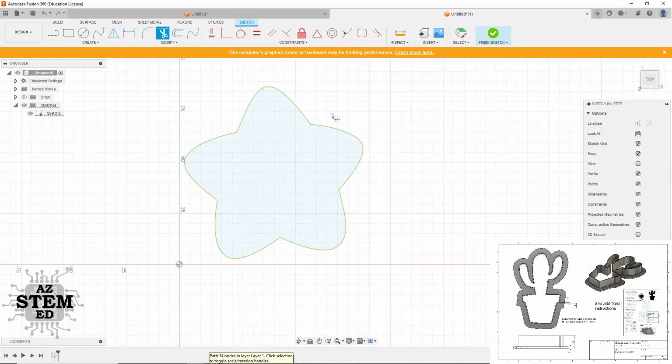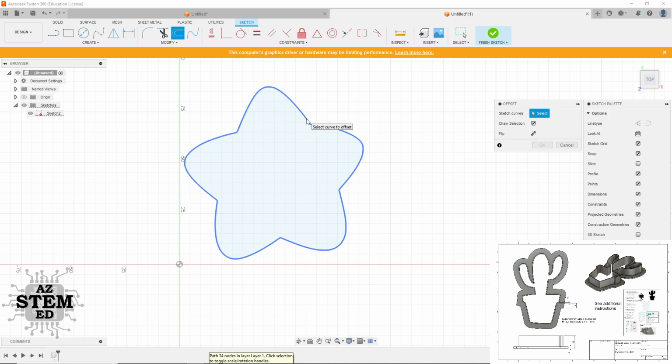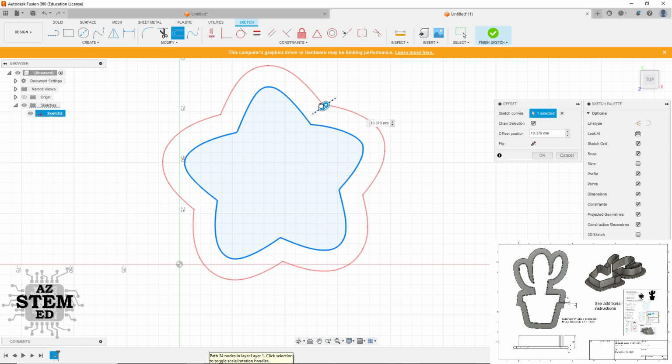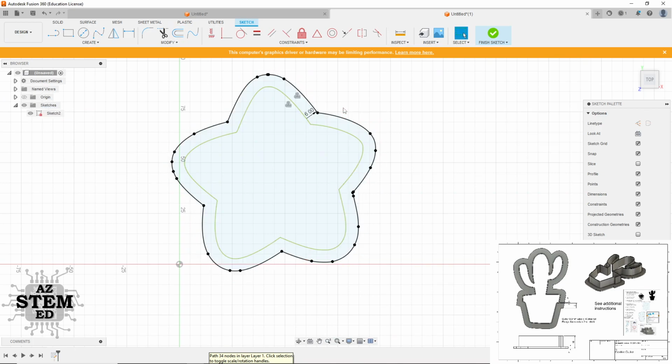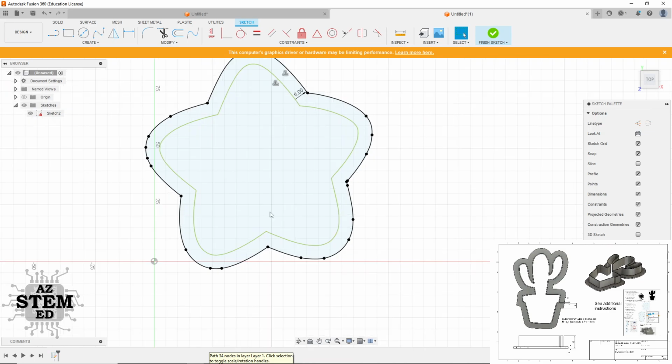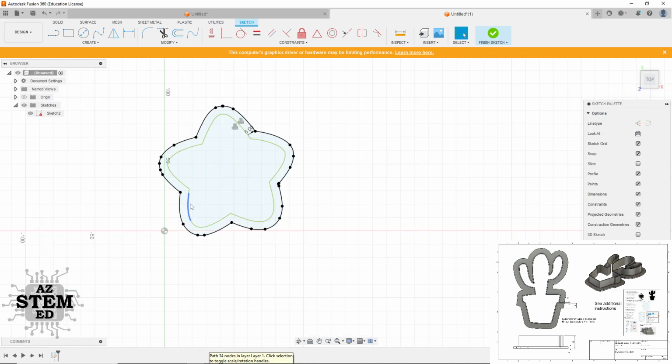Two things. One, we want to make a thin extrusion on this one, and we want to do an offset for the flange that hangs off the edge. Let's start with that offset, and that's in modify. We click here and then hover over the line until it turns all blue. Then I'm going to drag it out, and let's type 6. Good. This is enough to get started.